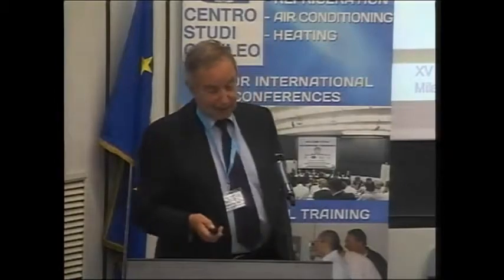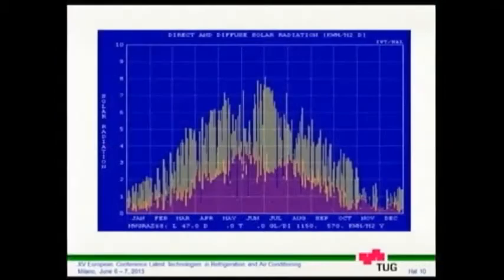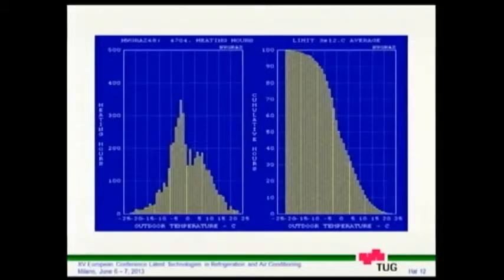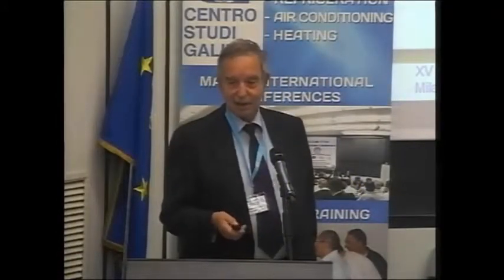If you take the climate, that's the solar radiation, that's the resulting temperatures, you get the temperature bins for the operation of such a heat pump in the heating mode, and this is a colder climate, it's Central Austria somewhere. And you can see you have the average somewhere at -2 degrees centigrade.